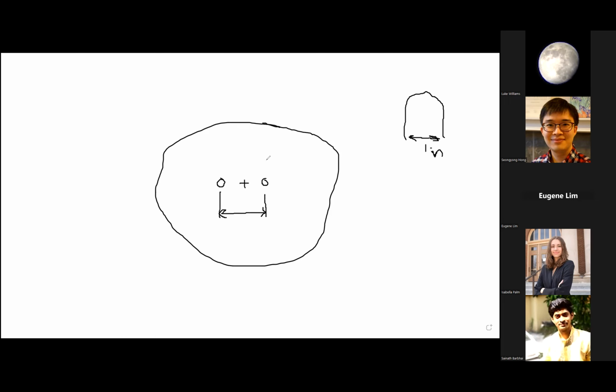So the ultimate moral of this is that whether to use series or parallel matters much more on the application of the part you're designing rather than just a simple rule to pick one or the other. And so you kind of have to think about what exact dimensions matter most for your part. Then you can decide whether you're going to use parallel or series for your dimensioning scheme.